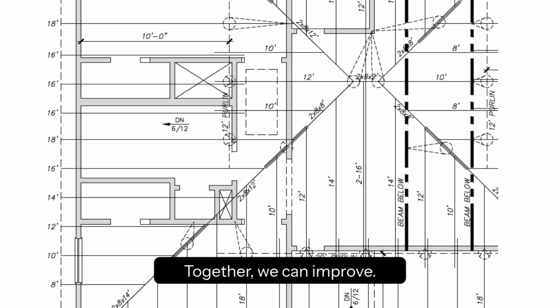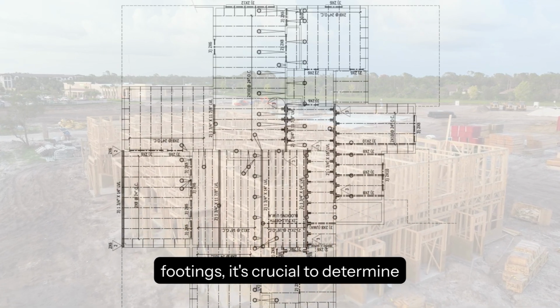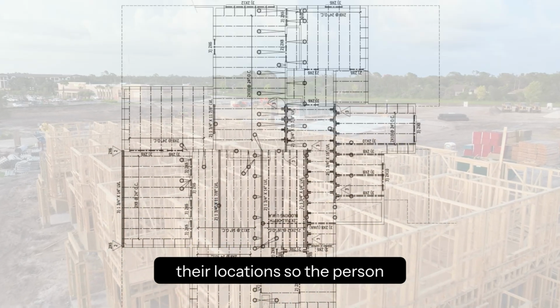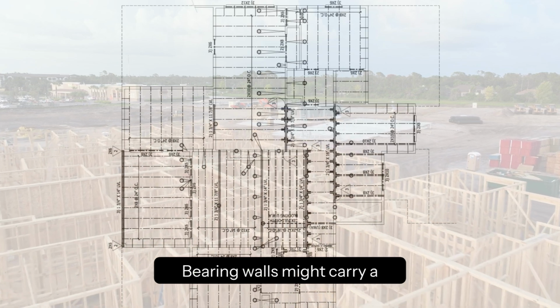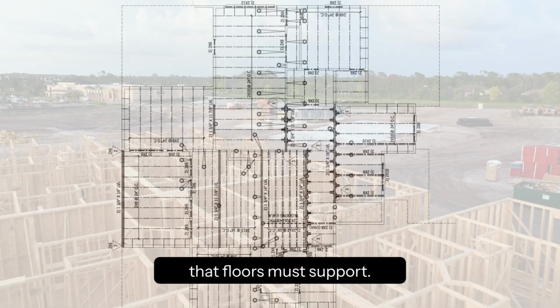To design walls, headers, and footings, it's crucial to determine how loads are transferred by the building designer. The plans should specify these loads at their location so the person designing a floor system can properly size the system. Bearing walls might carry a uniform load, while headers and beam ends may have point loads that floors must support.